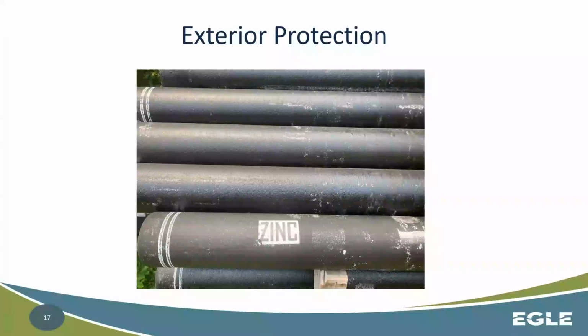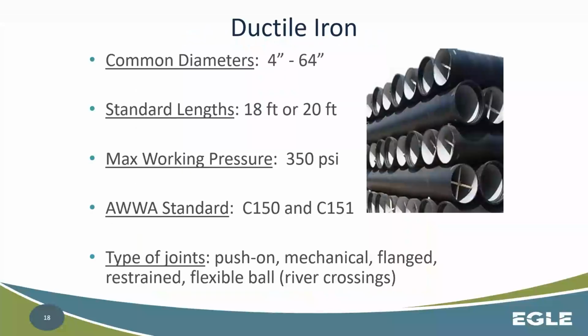Another example, as I just mentioned, is that zinc embedded external coating. Again, it just protects the pipe from a corrosive environment, whatever that is. So zinc is a sacrificial anode in these circumstances, and you're not having that same kind of breakdown of that material. You're not having a corrosion factor, at least on the external side of the piping.